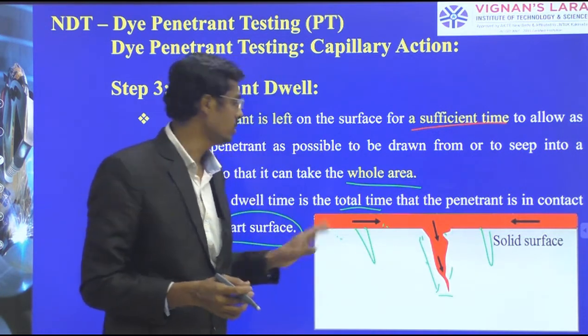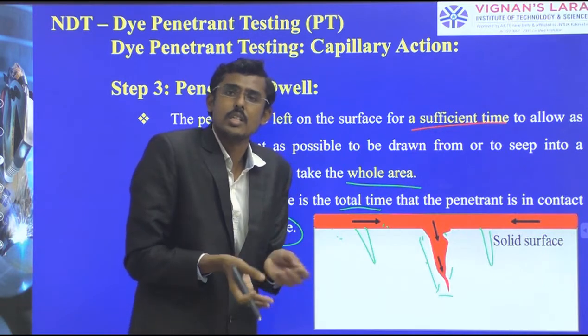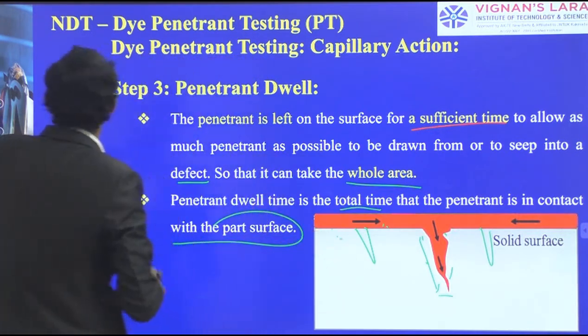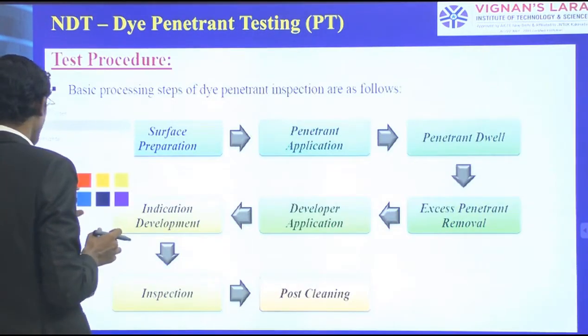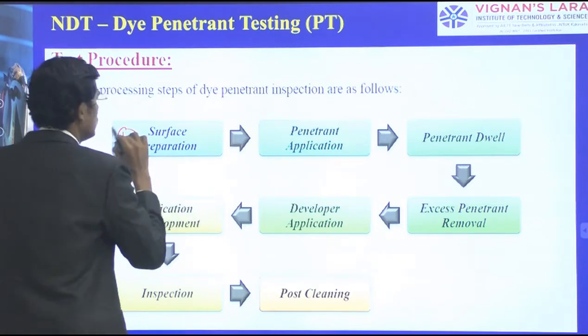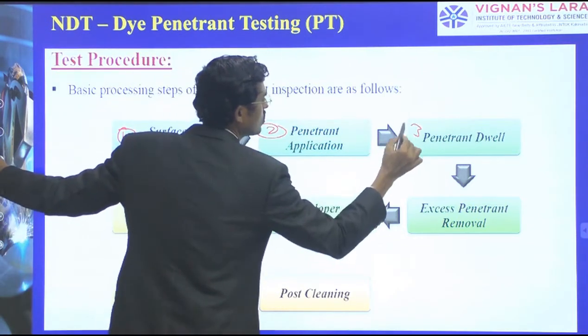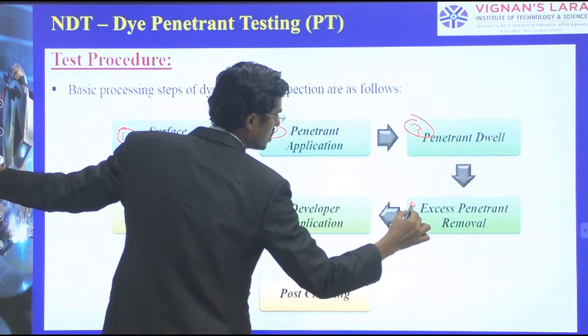Until the dwell time is given, the penetrant is in contact with the surface and the cracks. After that, we are cleaning, so there is no contact; it is removed already. So step 3 is completed, and we are going for step 4, the next one.